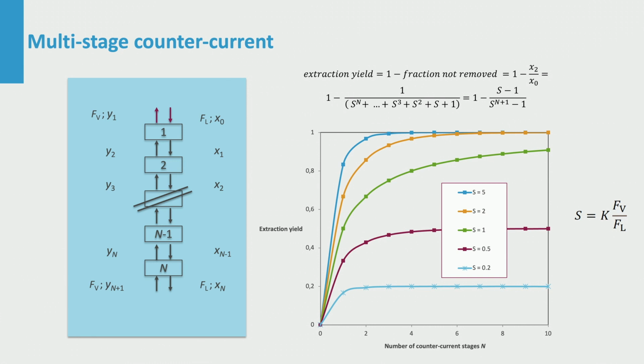A larger separation factor is achieved by choosing an auxiliary phase with a high K value due to high affinity for the compound to be removed, or by using more of this phase. More stages and more auxiliary phase also lead to more costs, and an economic assessment can tell if they are worth the extra product extracted.